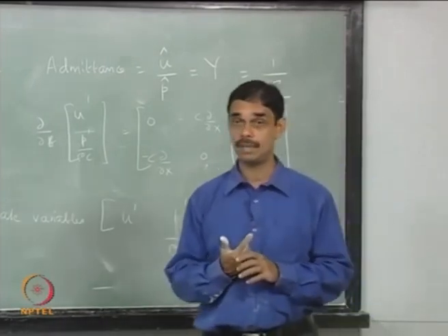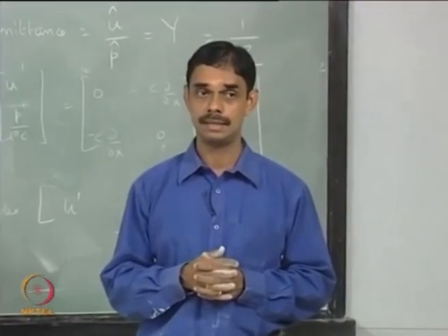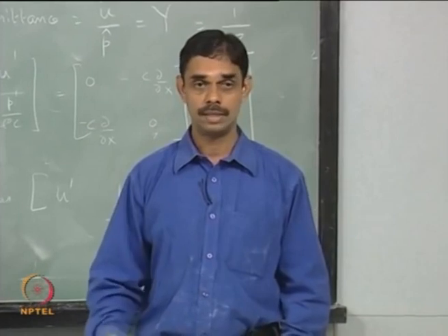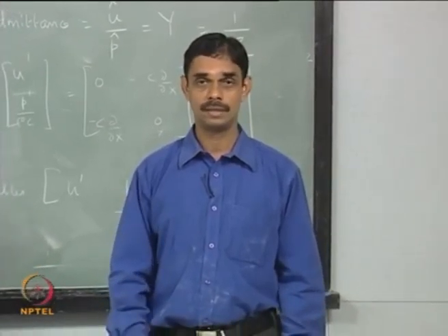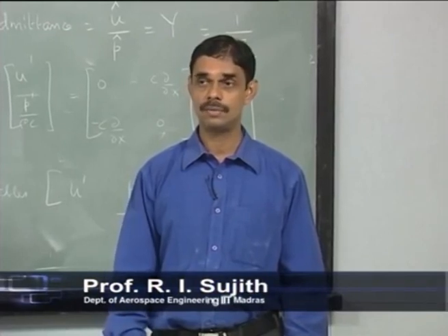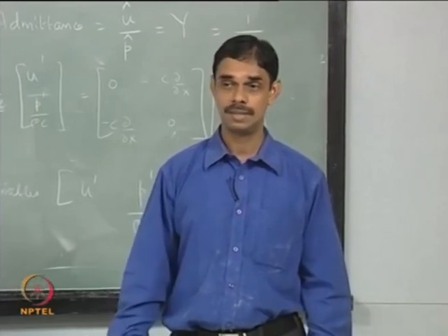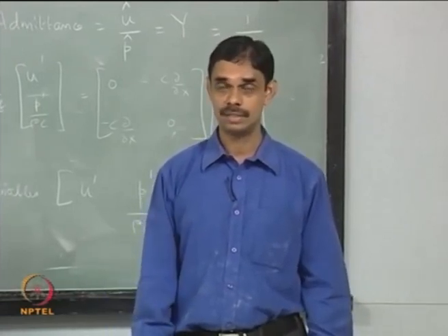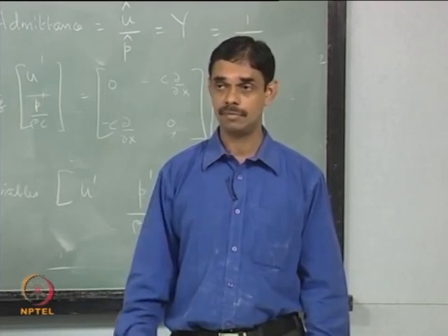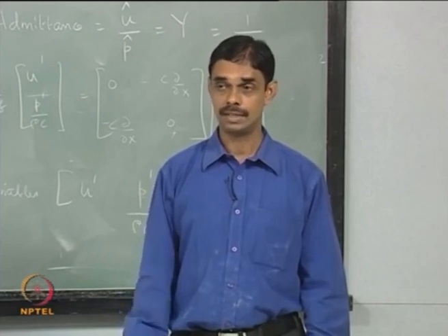So in summary, we have taken a quick look at standing waves in a duct, and we now know how to calculate the natural frequencies of ducts with open ends and closed ends, and we even thought of how this can be used to calculate quick estimates of natural frequencies of even such a complex thing as solid rocket motors. Then we ended with the definition of impedance and admittance, and we will see how that can be used to characterize the growth and decay of acoustic energy in the systems.